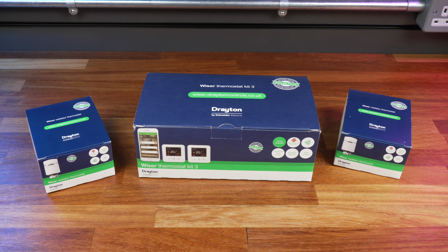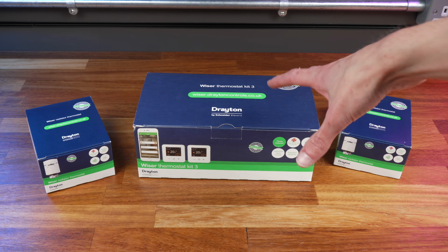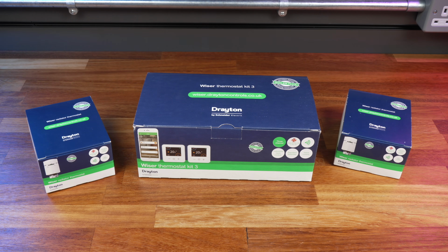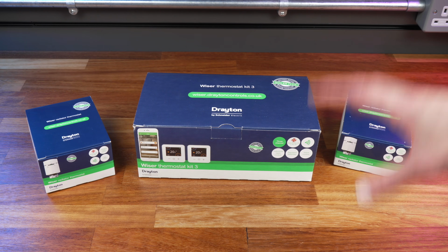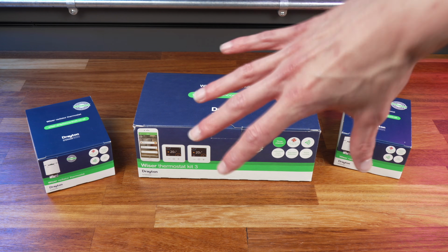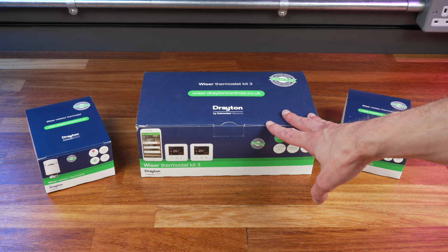Now for my system here, I have a combi boiler, but I have 2 heating zones. So for that sort of system, you need to use a 3-channel hub's 2 heating channel outputs, and then you just don't need to connect up the hot water channel. So just bear that in mind, because even though technically my heating system only needs 2 channels to operate, it needs to be the 3-channel hub, because on the 2-channel hub, the second channel is dedicated for hot water. It wouldn't work as a sort of second heating zone, so you need the 3-channel hub.